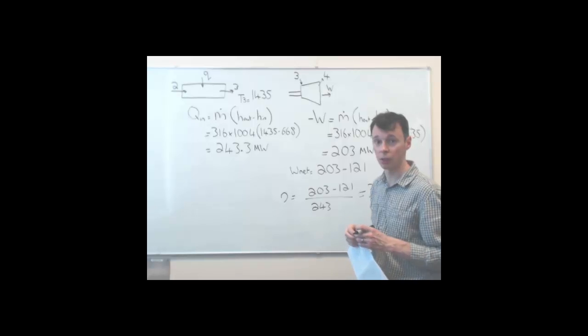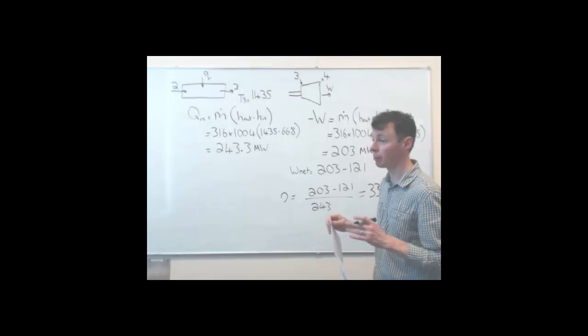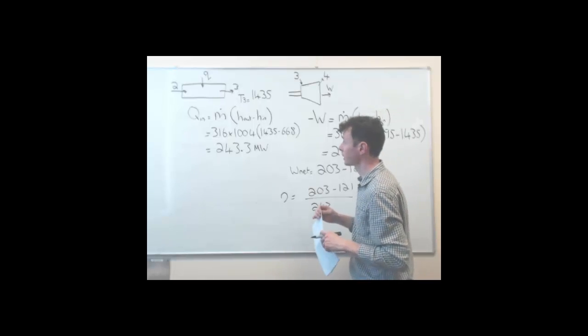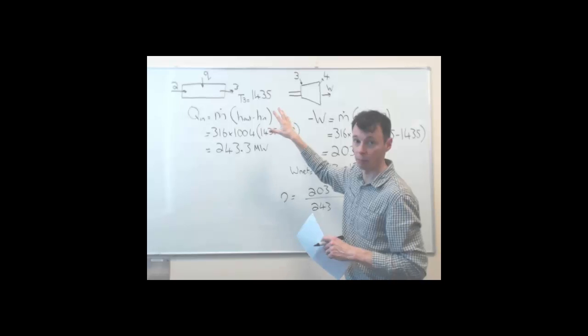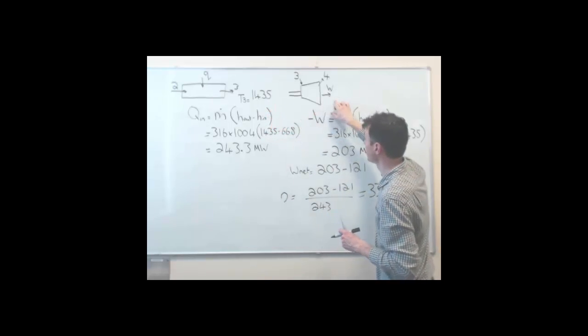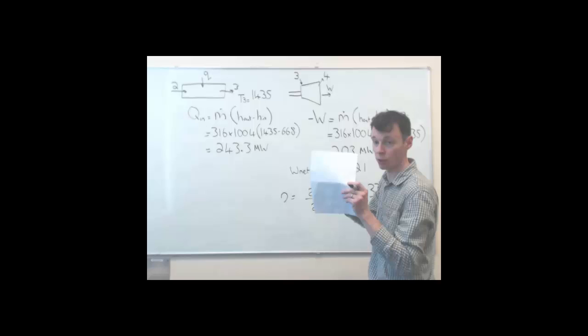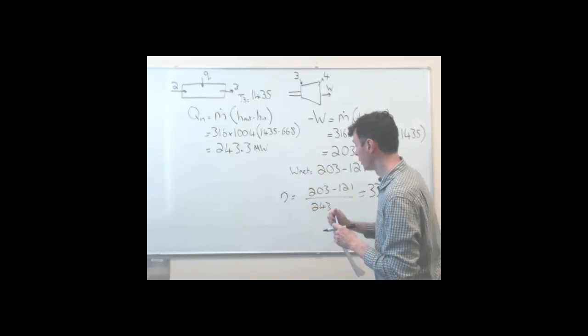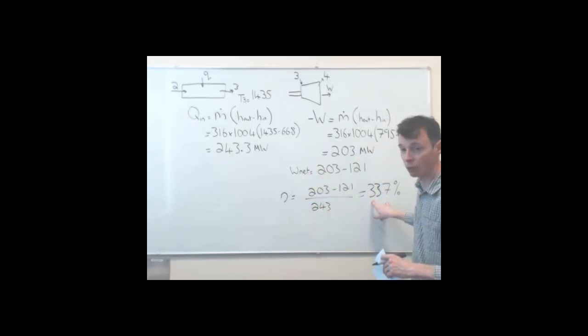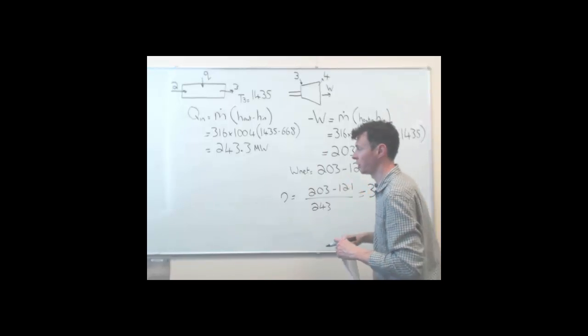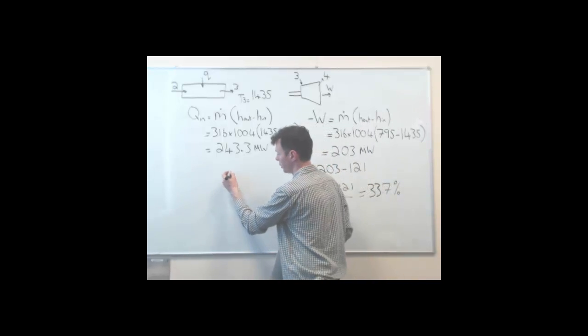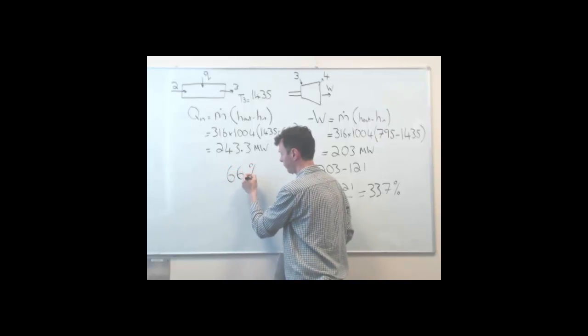So the steam expands out, and then we get a second bite, so we have a second cycle. So we have power stations in the UK and around the world that are called combined cycle, and they use gas as a fuel. So the gas comes in, we have a standard Brayton type jet engine cycle, and then with the waste heat we put that through a Rankine cycle. So they have two linked cycles together. So the Brayton cycle on its own is quite low efficiency, but then you double that up with a second bite of the cherry, so you get another cycle on here, and the combined station efficiencies for these types of installations about 66 or 67%.